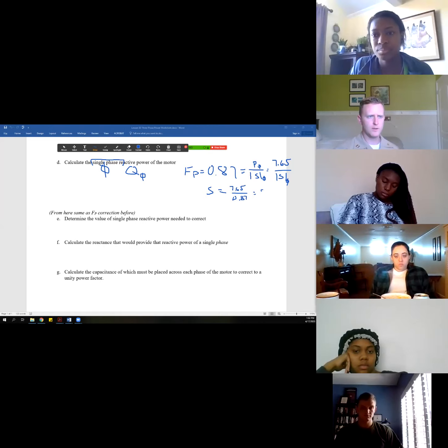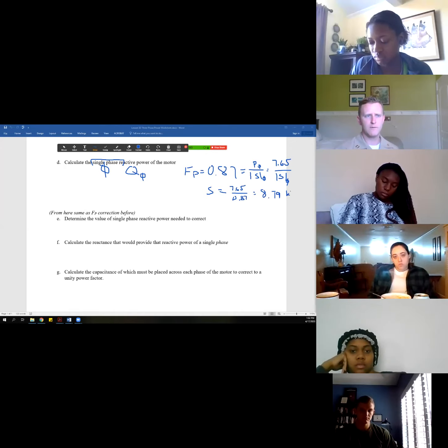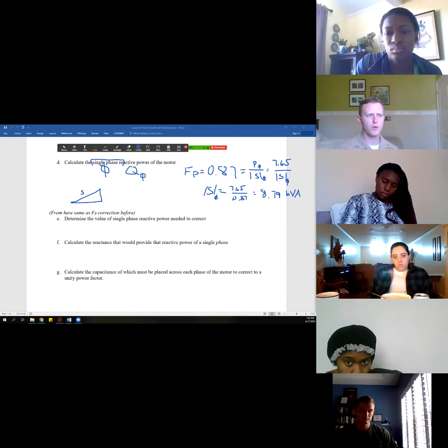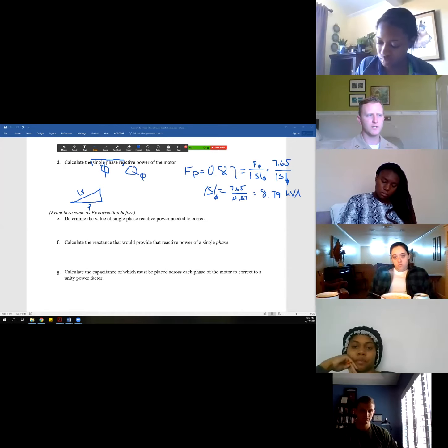And I get 8.79, and this would be kVA because it's apparent power, right? So there's the single phase of S. And if I think about this as a power triangle, there's a power triangle here. Here's S, 8.79. Here's P, 7.65.